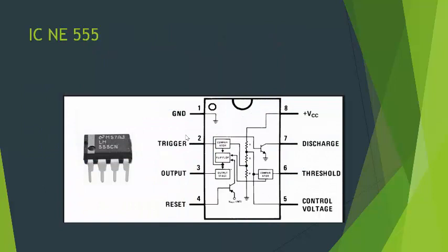Now the IC NE555 timer has a total of 8 pins: ground, trigger, output, reset, control voltage, threshold, discharge and VCC. Here in this circuit the IC NE555 timer is in monostable mode.